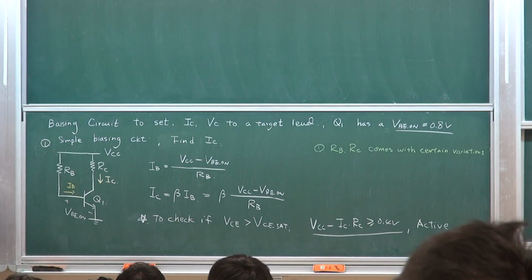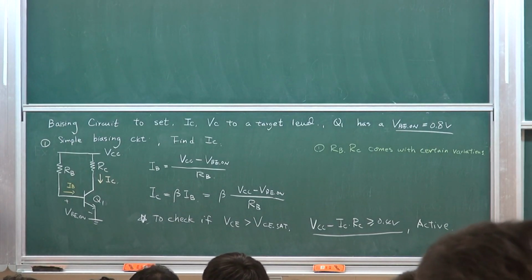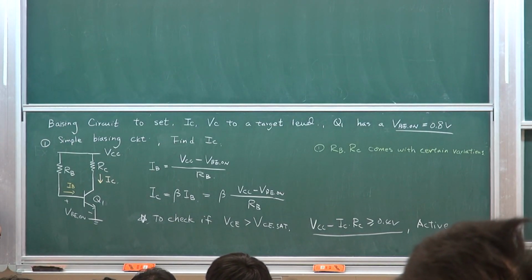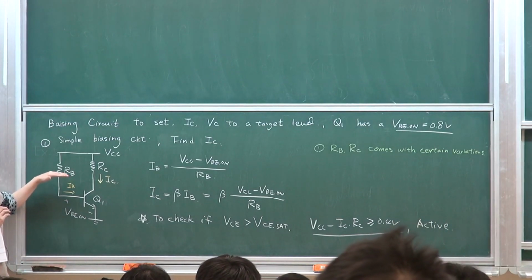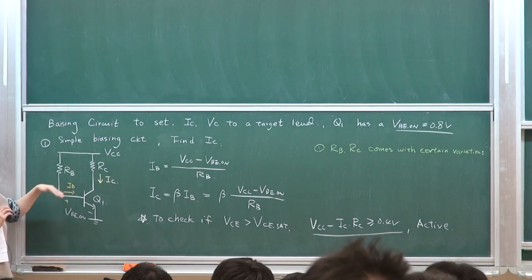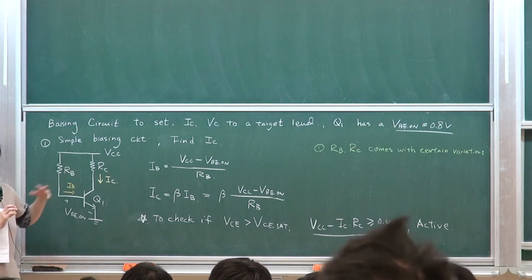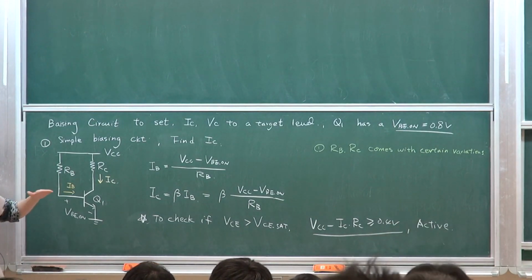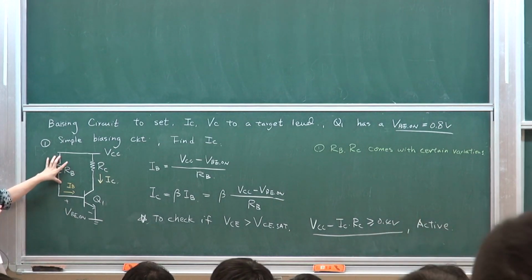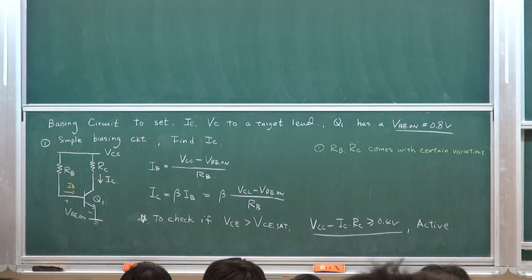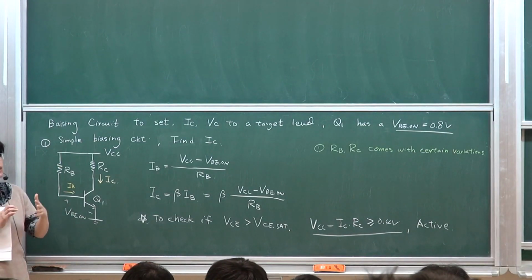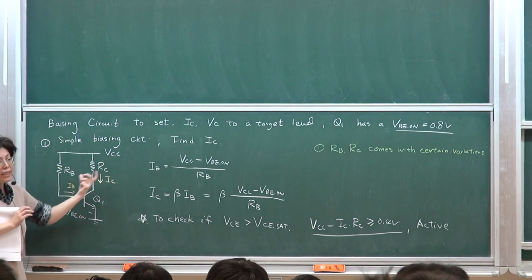If you ever did any integrated circuit design, you would know that there's a tolerance of resistance level. Most of the time, maybe 10% tolerance, meaning that if I'm designing this to be 100 ohm, it will be 80 or 150. It will not guarantee to give you a precise number. The precision level of the resistance value is very hard to get. So you have to live with a possible variation in these elements.